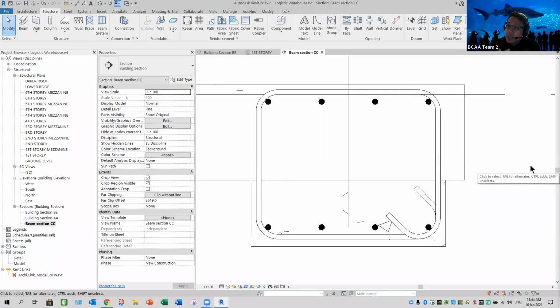Now, this is only when you're displaying at the section view, because when you cut your concrete, you don't just see the cement, the structure, the concrete inside. You should see the rebar. So whenever you cut a section view, not a building section, but a partial view like a beam section, slab section, or column section, you must add the rebar component inside. This type is a must.